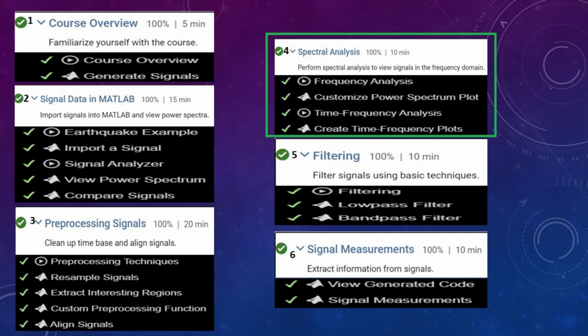B. Customize power spectrum plot. Task: display power spectra of all three signals and set the frequency scale to log. Comparison: HARP and PAX have similar low-frequency content, while Wrangell contains high-frequency components.